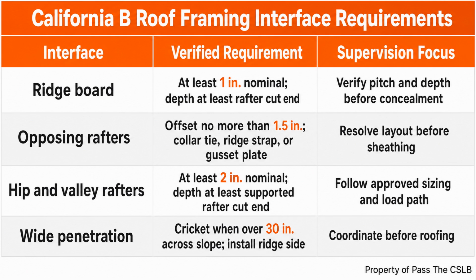Slope also controls whether a roof covering can be used and how the underlayment must be installed. Asphalt shingles require at least 2 and 12. That is an absolute minimum for the rule in this lesson. Calling a roof nearly flat does not create an exception, and adding more nails does not turn shingles into a low-slope membrane system. From 2 and 12 to below 4 and 12, asphalt shingles require the specified double underlayment application.